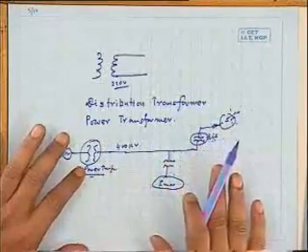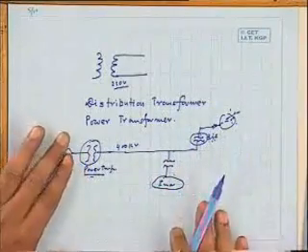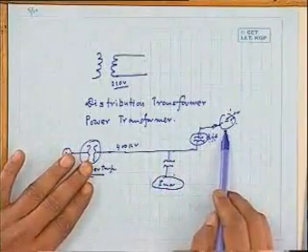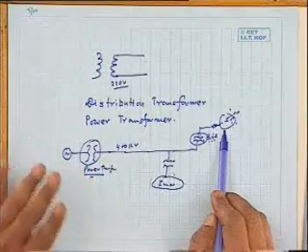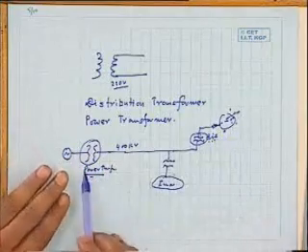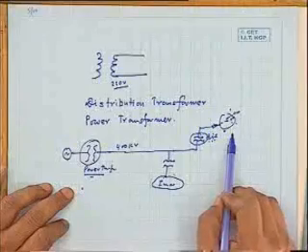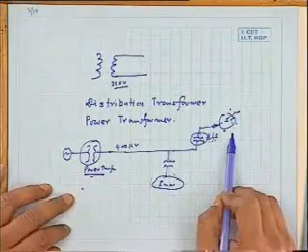So if you compare the operation of these two transformers, we immediately understand that while this transformer will undergo severe changes of load round the clock, this fellow will not. Maybe its load variation on the secondary will be between say 95 to 100%. I think I have been able to make that point. Therefore, for this transformer, we would like to have X closer to 1 compared to this transformer.